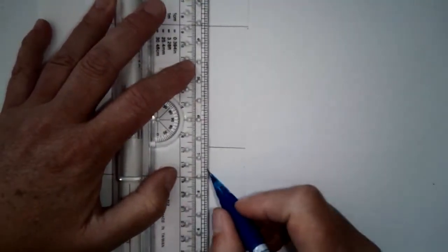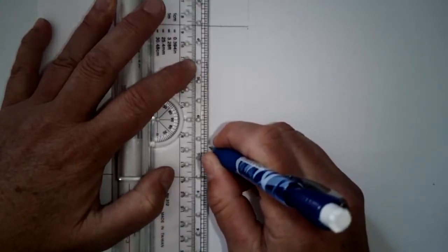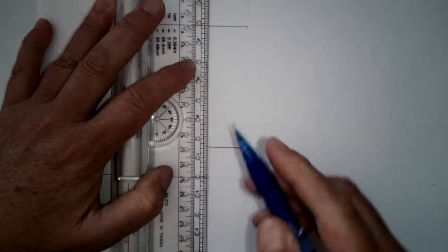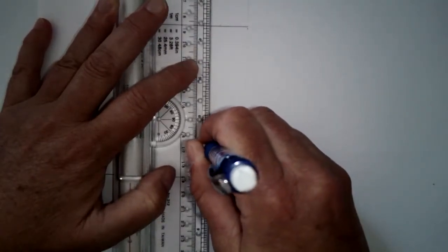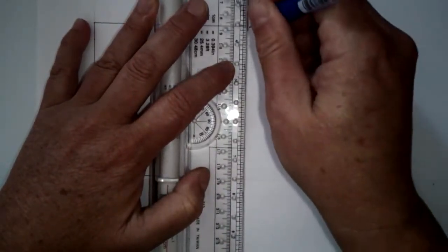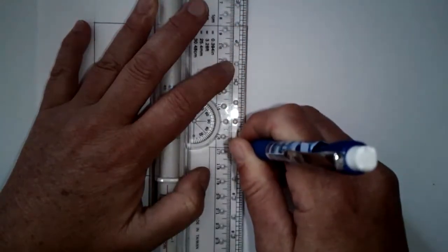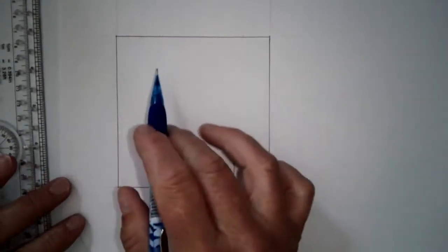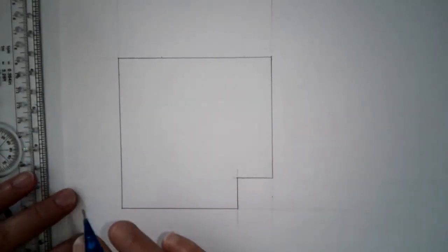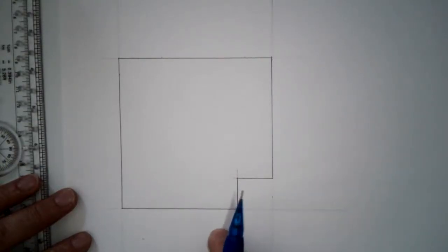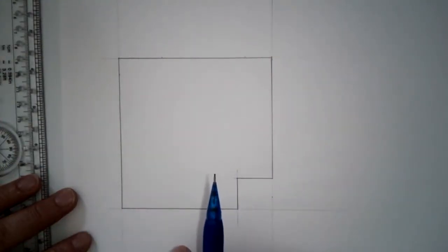I'm going to go to the next vertical line I can use, using the construction lines here. So I've got construction lines that show me exactly where to position my lead and then where to stop it. And then the last line that we have here from those intersections. So those construction lines are driving where I end up putting all that line work. So the construction line step is extremely important. If you do them correctly, you don't have to go back and erase them. It's perfectly acceptable to see the construction of this drawing as it goes forward.